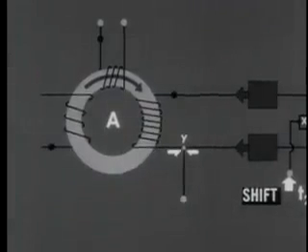There is a counter EMF induced in the winding when the pulse is applied, but because the change in flux is so slight, the counter EMF is negligible. As a matter of practice, however, a small coil is inserted into the lower connection to provide a counter EMF there that will balance the counter EMF in the output winding. Therefore, the upper branch pulse meets no more impedance than the lower branch does. The impedances are equal, and so the branches are equal. At point Y, this upper branch current joins the lower branch and flows out of the loop.